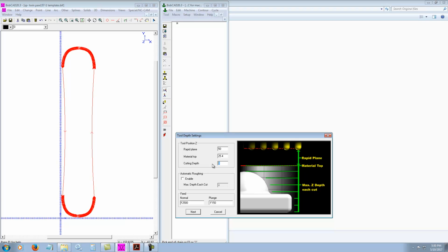But I usually like to cut almost right through it, because that doesn't run as much risk of the bit damaging the tabletop. So what I usually do is I put a number like 0.2 millimeters. So it's going to go all the way through the material and then stop just 0.2 millimeters shy of the table, which is just this tiny little paper thin layer that is very easy to just sand off of your template or whatever when you're doing it.